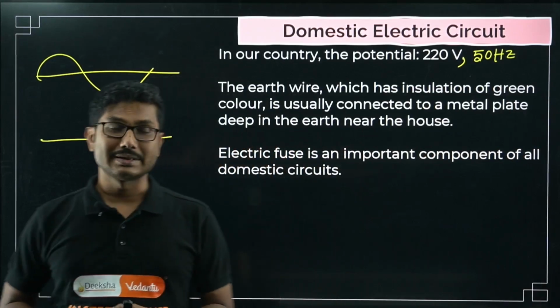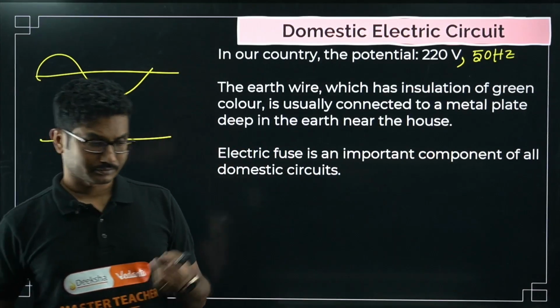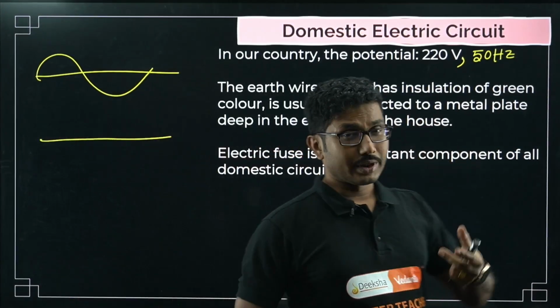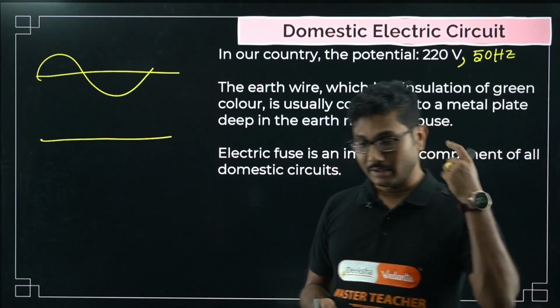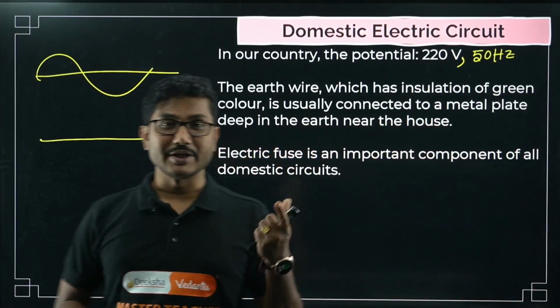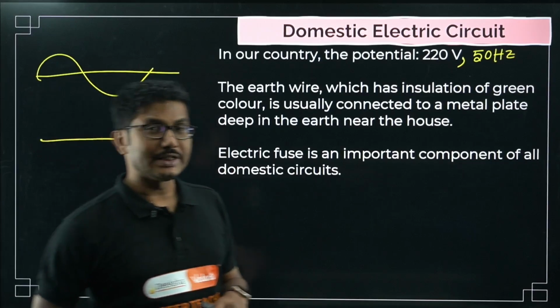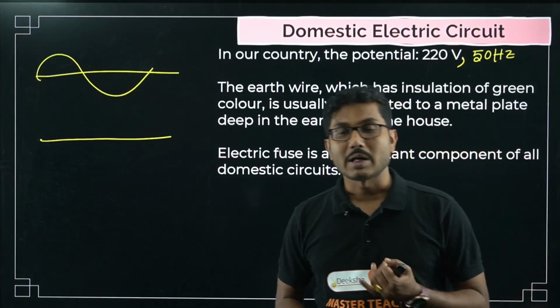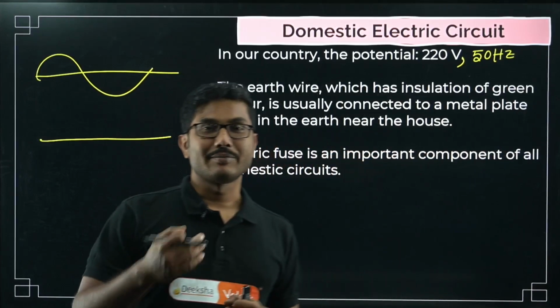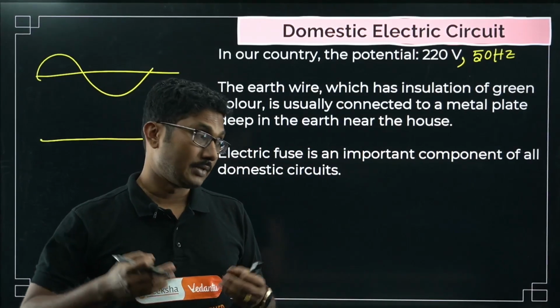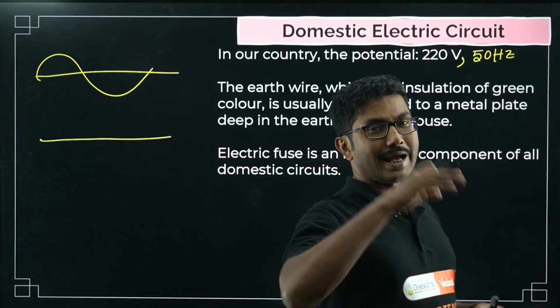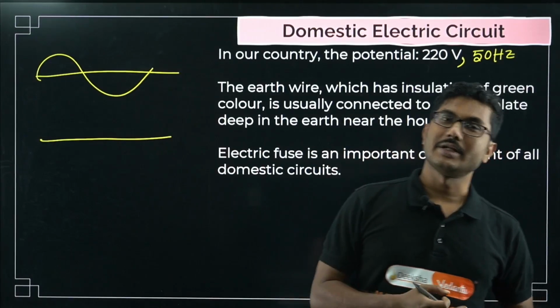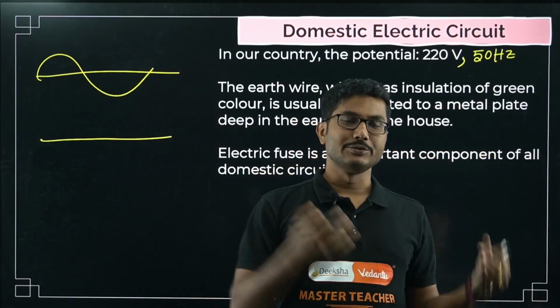There are some devices which convert AC to DC and then utilize it. One example is modern televisions, not the older generation CRT monitors. Modern televisions first convert AC to DC, because the electronics inside the TVs are not compatible with AC current. They can only use direct current. So they have some mechanism inside which can rectify the AC to DC.